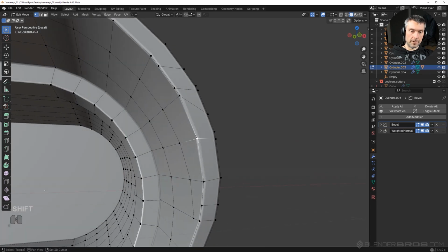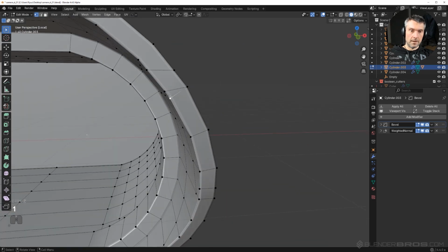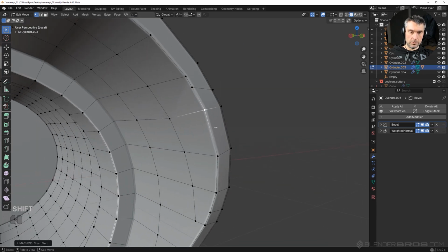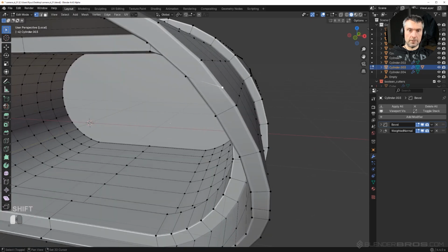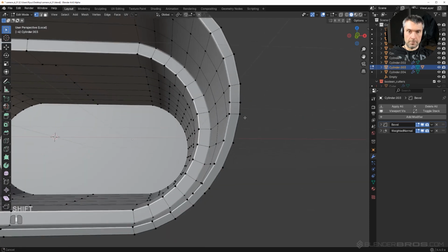Clean up all the verts here that are really close together. Do that here, right? And let's slide it down a bit. This is going to allow you to run much cleaner subdivision. I'll show you in a minute. It's going to work perfectly fine on this side, and the other side you will need to do the same, or simply run a mirror, right?